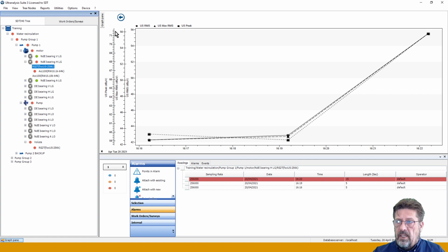There is a scale for each of them here, and remember from the beginning I told you we set the scale to auto. So we didn't define what will be the maximum, so we say just set it on auto. And this is why they are all somewhere close to each other. So they are in the same level, because you can see here the peak is 64 here, and in this case particularly it's 60, and this is somewhere around 43.5. If we set up the scale differently, it will be shown depending on the scale we define.